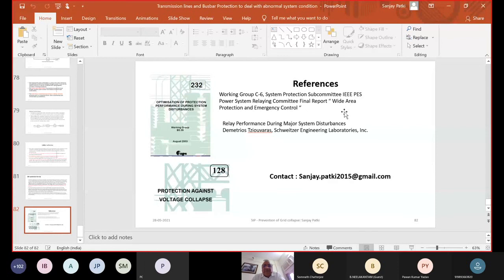So go for main 1, main 2. For 132 kV, if it is a critical line, you need not have separate backup protection again. It can be combined with main 1, main 2 in both. Our line length is only 14 kilometers, sir. And that's fine. Whatever protection you can have, duplicate protection, if that line is critical to you.